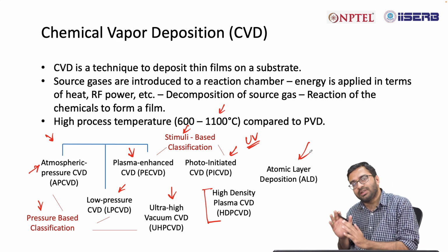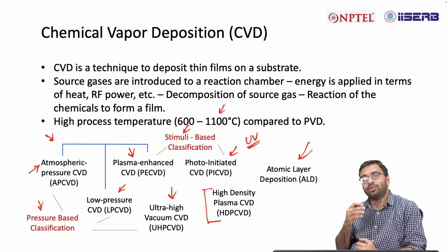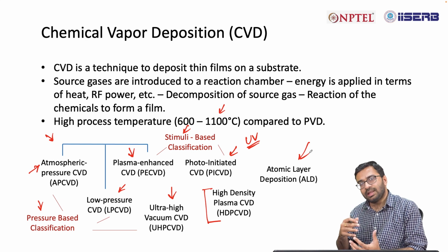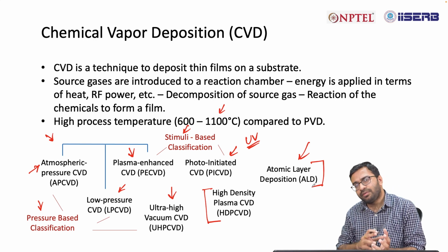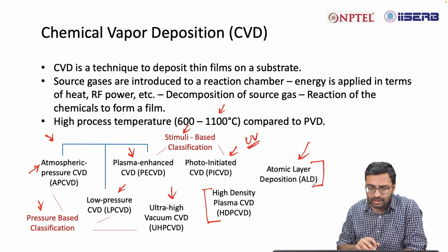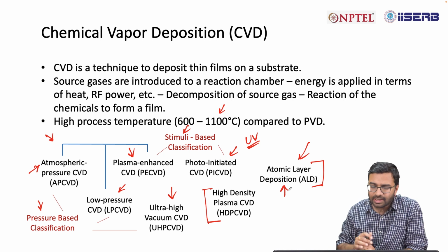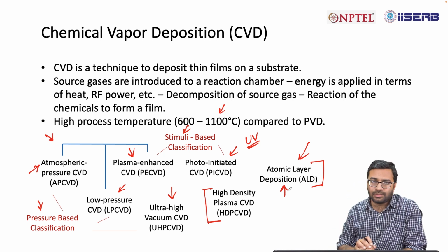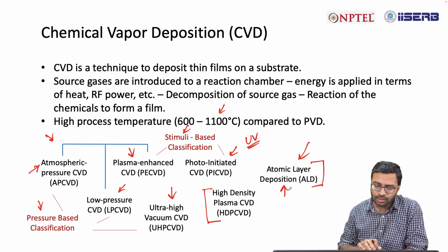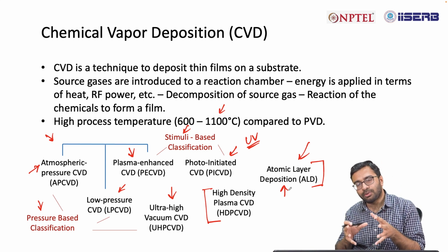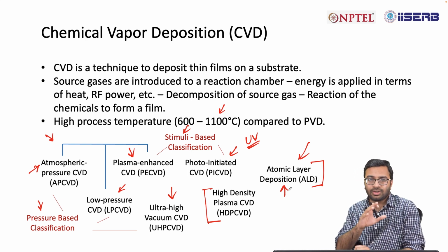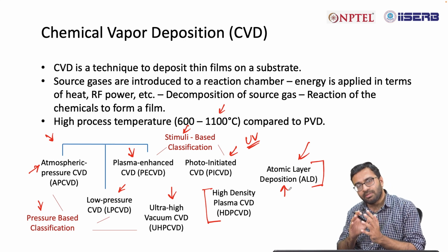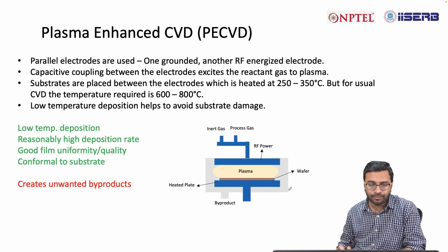This is also a kind of CVD technique, but in this case you insert the gases sequentially inside the chamber. So, this is a kind of CVD technique, but a bit different. With this particular technique you can create a very thin layer of films. If you want that, you should use the atomic layer deposition technique. But in all these processes the basic principle is the same. The 7 different processes or steps that I have shown will be followed in all these CVD techniques.